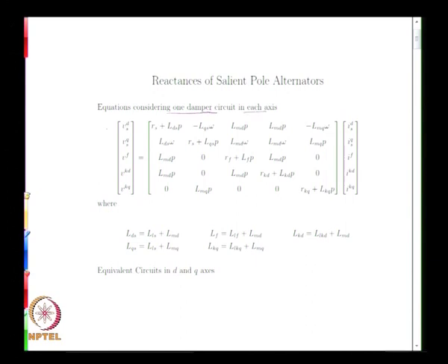We have here the d axis equation, V d of s, that is when we represent it this way, it means that the voltage along the d axis attached to the rotor, but of the stator variable. So similarly you then have voltage of the stator along the q axis.